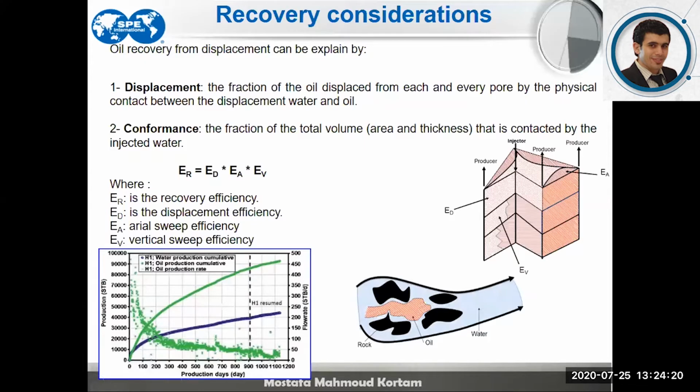It illustrates and demonstrates that there is some amount of oil that is unrecoverable, which should be produced. Such oil that was not recovered by the secondary recovery is really a significant share of the oil, and that may impact losing some of your reserves.